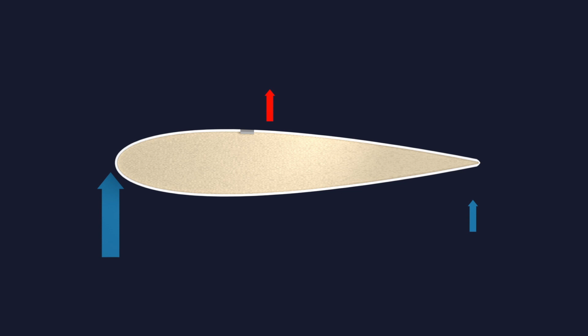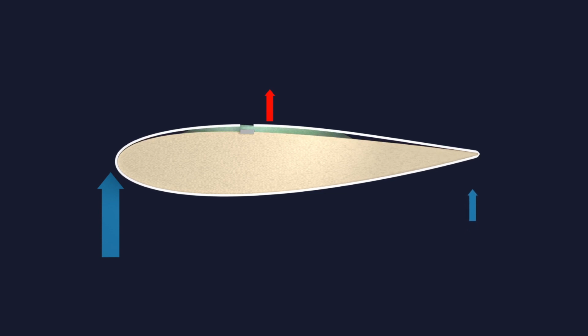Keep in mind that Canis lives in the Chesapeake, where it freezes in winter. So as soon as water trapped under the skin froze, it expanded, creating a wedge which further detached the skin from the foam. The following year, more water got trapped and even more damage was caused during winter.